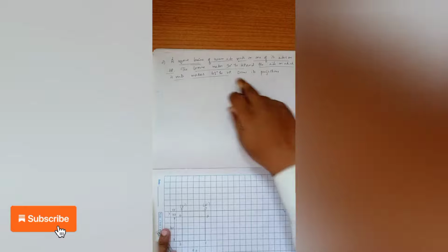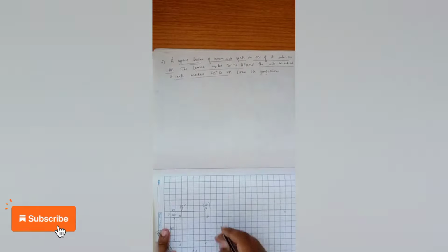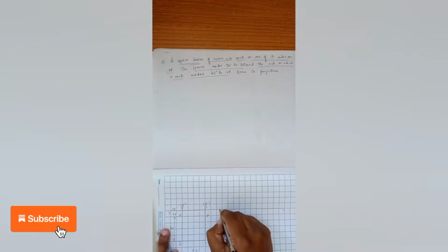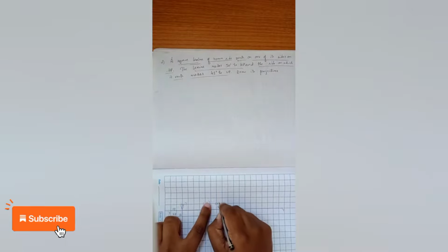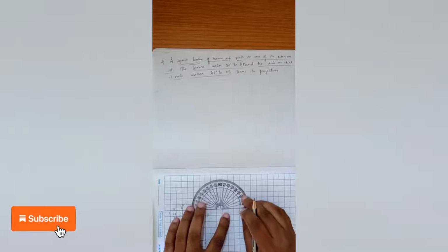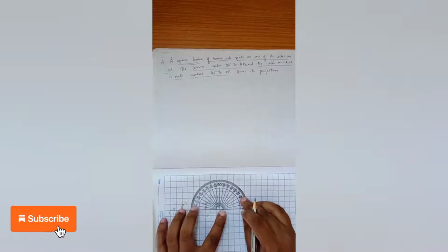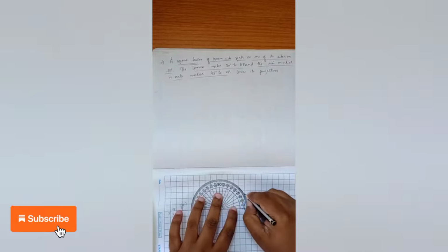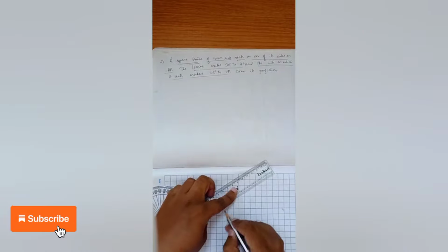Now we proceed to the second position. You can see that the lamina makes 30° to HP. So first I will take a reference point here. The reference point is B dash and A dash. Now we have to show the inclination, that is a 30° inclination we have to take. Exactly mark it here, mark 30° and draw a straight line.